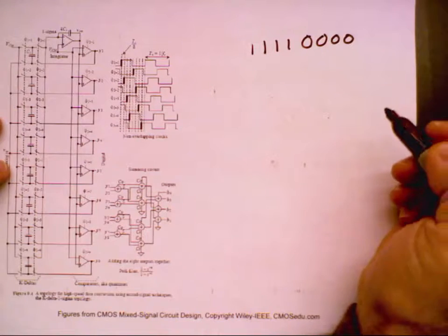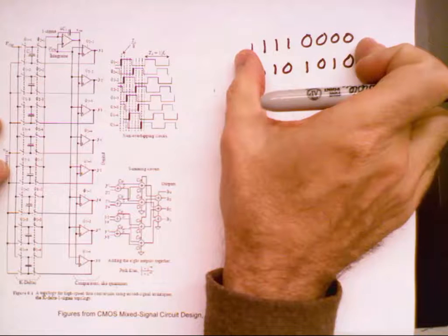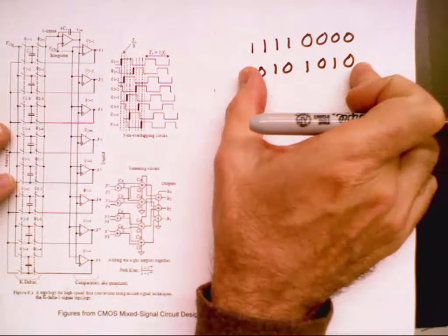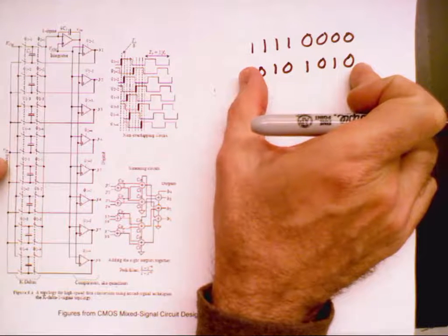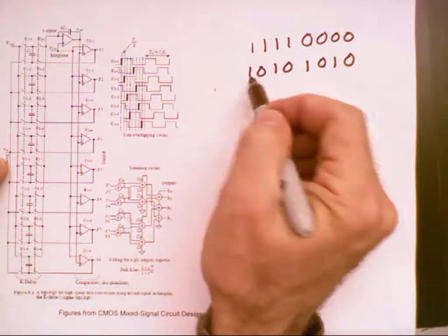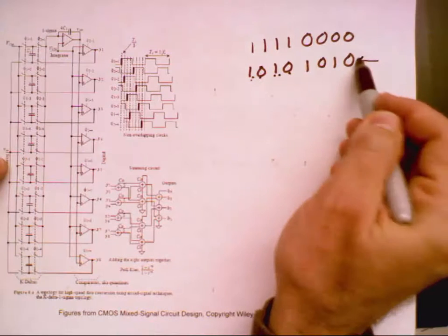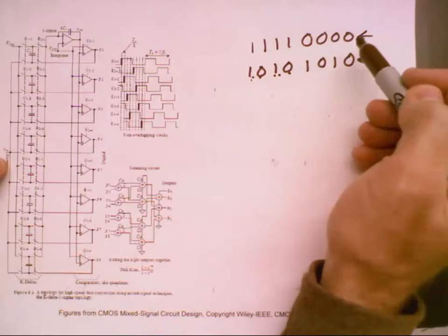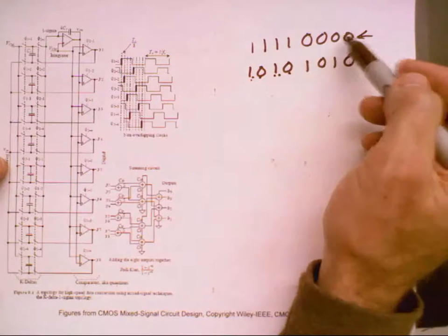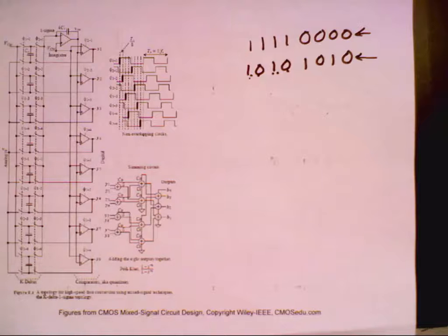1111 0000. Okay? 10101010. In parallel mode, I add up the number of ones and divide by the total number, and I get 1/2. These are different signals, right? If I look at them as they're coming out at a real high speed rate, in serial, then I get a different response between the two. When I add them all together, I'm effectively decimating the output because it's coming out after 8 samples. With decimation, I'm going to get a little aliasing, and that's going to increase the noise.